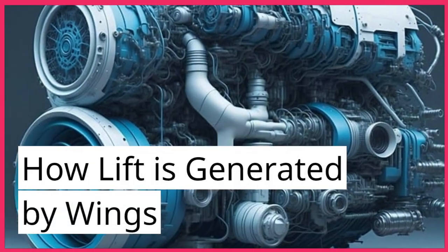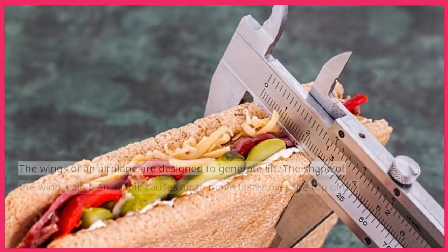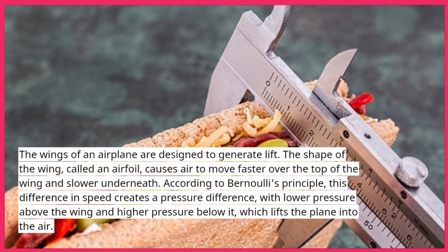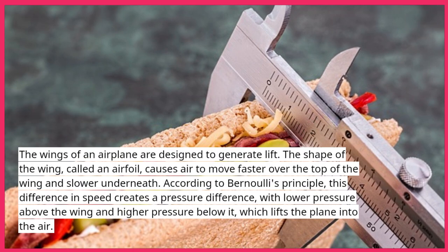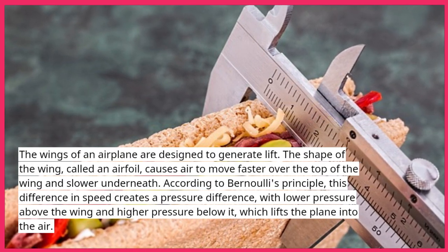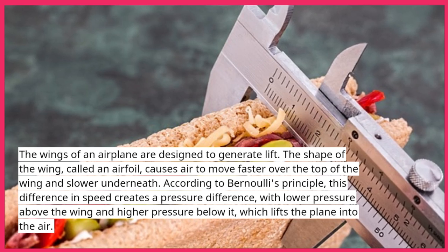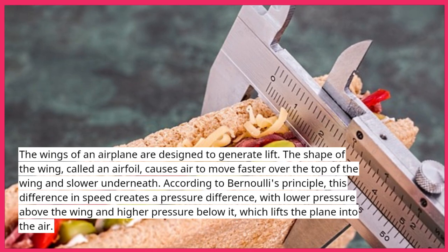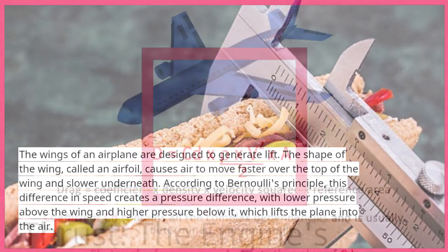How lift is generated by wings. The wings of an airplane are designed to generate lift. The shape of the wing, called an airfoil, causes air to move faster over the top of the wing and slower underneath. According to Bernoulli's principle, this difference in speed creates a pressure difference, with lower pressure above the wing and higher pressure below it, which lifts the plane into the air.